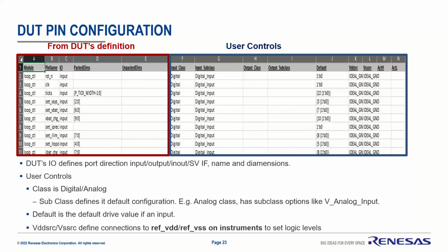Another question: how much randomization do you use in DMS versus AMS? So the randomization is actually done by a colleague of mine. Full randomization. We create the DMS tests that are randomized and then literally run the same ones in AMS. There are some specific directed tests in AMS that you'll want, like analog test bus checking, but if you've got, say, 10 LDOs that could start up in a sequence, you want to randomize the order of that sequence and just check that there's nothing wrong. So you do that in DMS and just do the same in AMS. Got it. Okay, that makes sense.